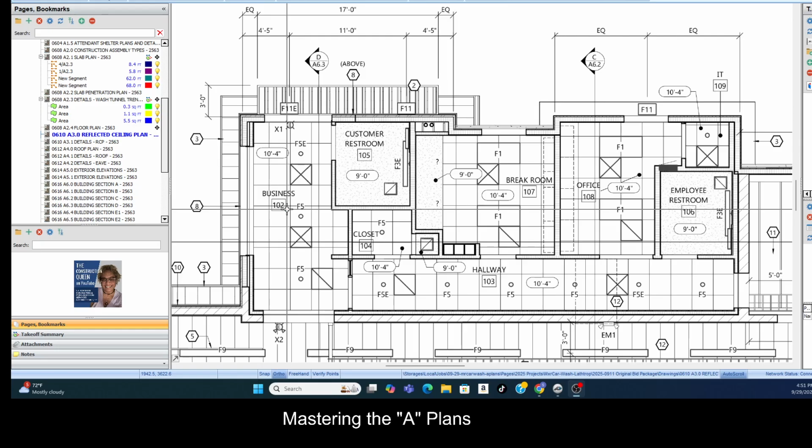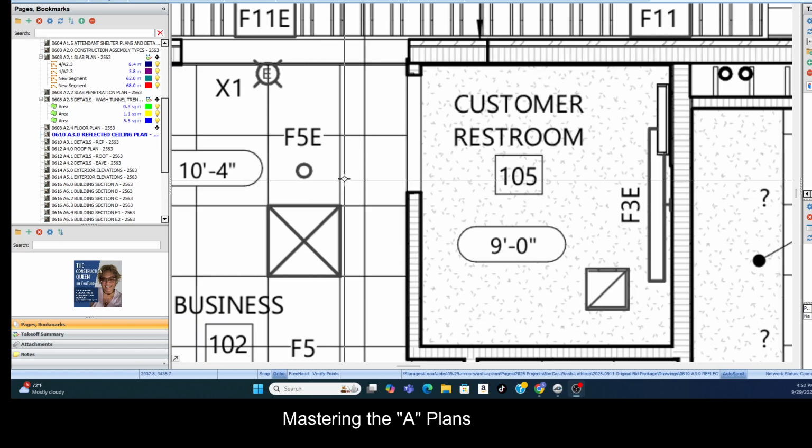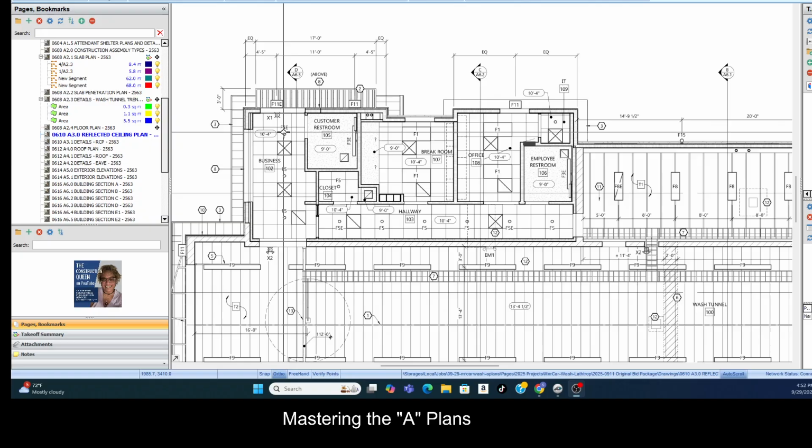Well, we see everything else because the ACT professional needs to know how many spaces will be deducted in that room for supply grills, return grills, or how many of the ACT tiles need to be adjusted, fitted for things like down lamps and stuff. Okay. And so, yeah, that's why we show everything.